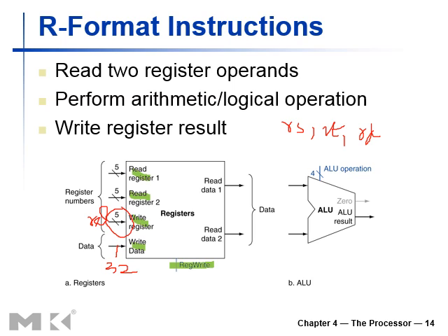And operands are read here. For example, if we have to read the value of RS and RT, we provide the addresses here, 5-bit addresses or the location addresses, and the data within those locations are being provided here. So this is 32-bit, and this is also 32-bit. Similarly, the ALU processes the input that is also 32 bits. And this is also the signal that is being generated by the control unit. So these are the primary interfaces that are being provided with the registers and register file or the ALU.